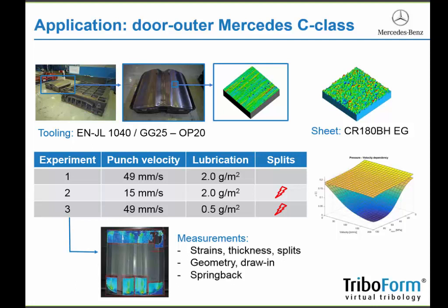So at Daimler, they did different measurements. They did strain measurements, thickness measurements. They did geometry measurements to compare the geometry, spring back and draw in. And we have used this information in this project to validate the Triboform friction model.